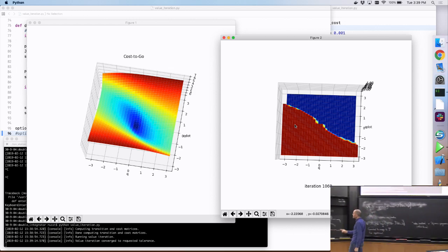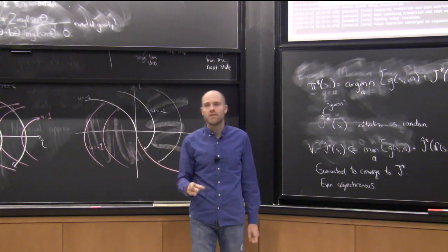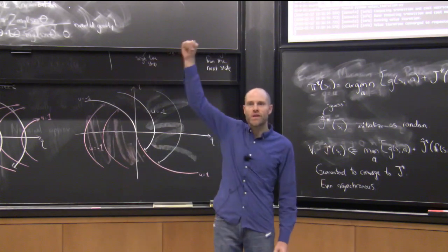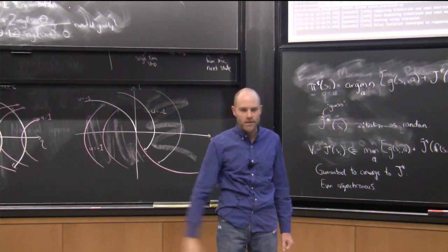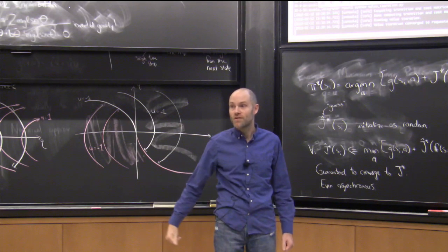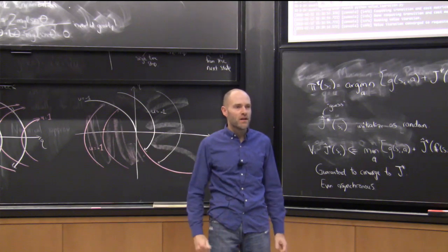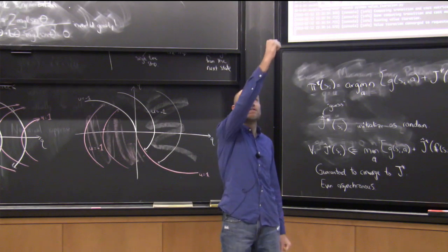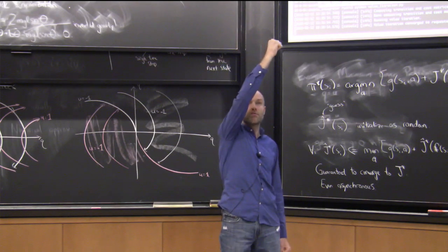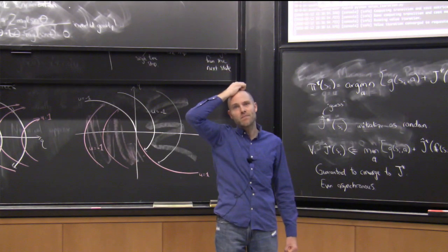So what is this, if we did the same thing now for the pendulum? I claim that the pendulum is actually pretty tricky, right? You have to swing up and balance. You want to pump just the right amount of time so you get there as fast as possible. You're probably going to ride on your actuator limit most of the time. But the places in state space where you'd cut from going from one direction to the other are subtle, real subtle, right? So, for instance, there's a state right here near the top where I have enough control, I'm just going to go straight to the top. But there's a neighboring state where I've got to go all the way around to get it, right? So what is that going to look like in state space?